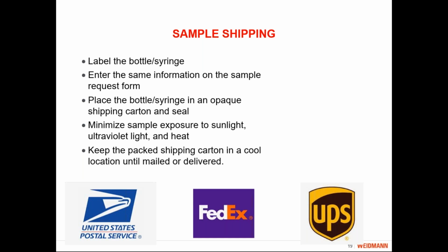Also, the new DGA guide actually needs to know what the year of manufacture of the transformer is so we can calculate its chronological age. And so be sure when you fill out your sample forms that you're adding that year of manufacture in if you can. Make an effort to fill it out.